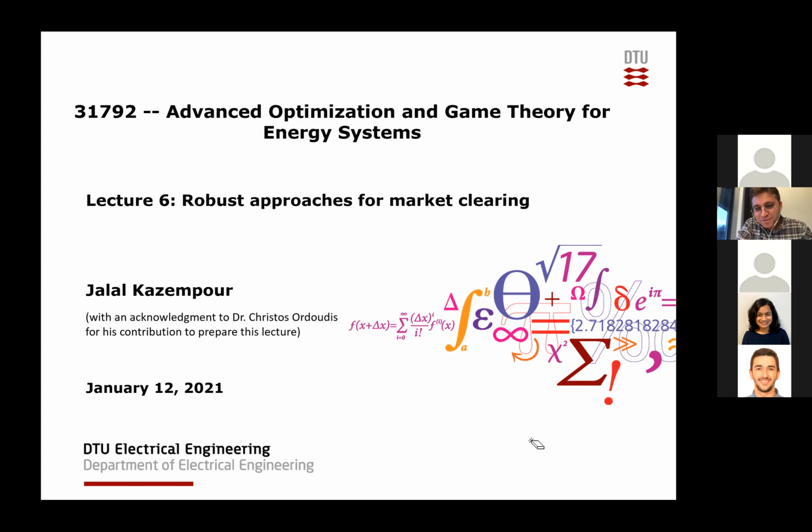Also, the production cost of G1 is $10 per megawatt hour. So it's 60 times 10, it's 600. 600 plus 600 is 1,200. Then we see that under real-time scenario 1, the wind production is 30, which is exactly the same as the day-ahead dispatch of wind. So it's unchanged. There is no wind deviation in real time. So then there is no change in the schedule of G1 and G2.